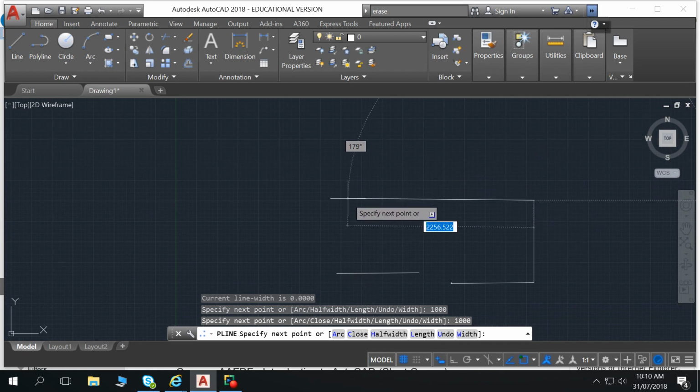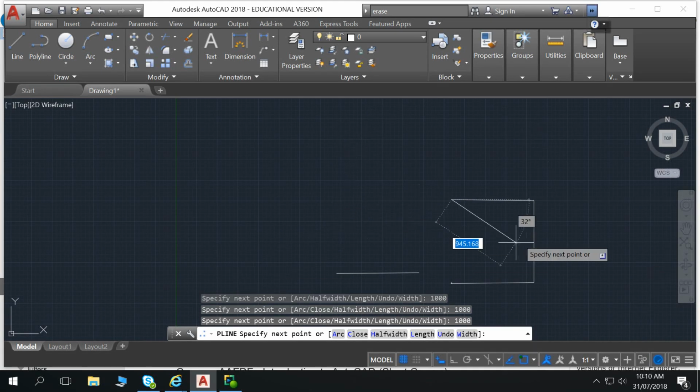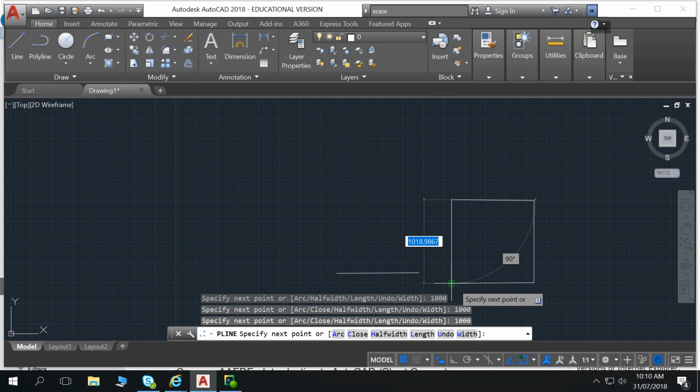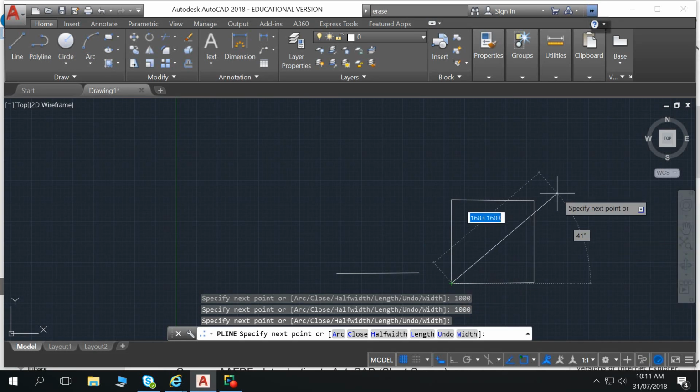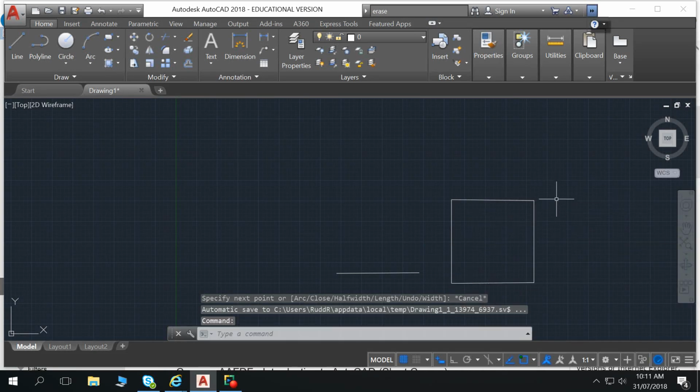And I want to go this way to the right, a meter. And I can either hover over the end point or my start point to close the object, or I can, as I said to you, press C for close, or just hover over that and either right click or press enter or spacebar. Okay, and escape. And there you have your first object.